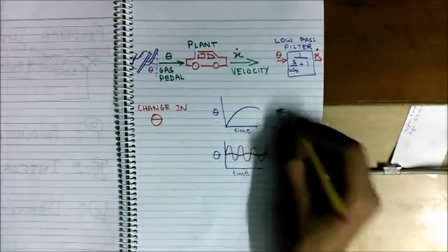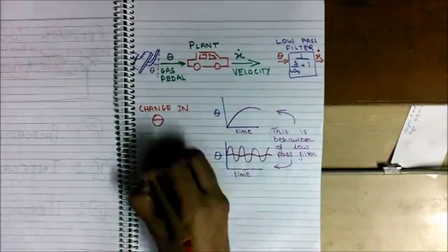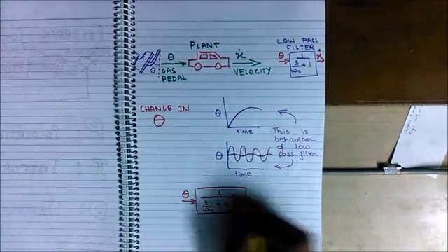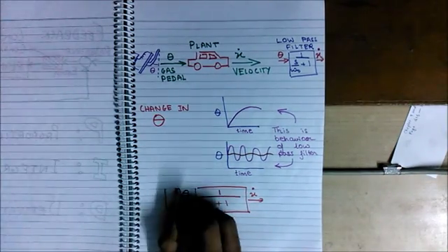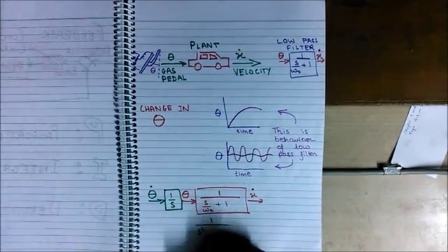But while driving, we don't set theta to specific values. What we take care of is the rate of change of angle. That is why we introduce an integrator to get theta from theta dot. Now, let us discuss the use of proportional control.